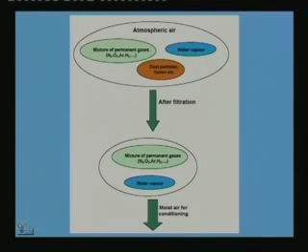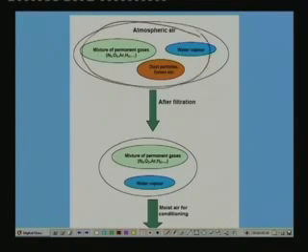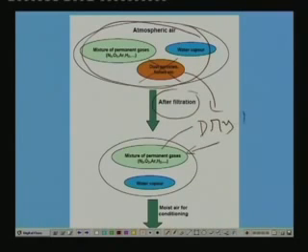So, as I said, this entire thing is your atmospheric air, but in a typical air conditioning plant, what is done is, first of all, we filter this air. When you are filtering this air, you remove the dust particles, fumes, etc. Once you remove them, you are left with a mixture of permanent gases, and you call this portion dry air, plus water vapor. So, this is what is actually processed or conditioned in an air conditioning plant. This mixture of dry air plus water vapor is sent to an air conditioning plant for conditioning. This mixture is called moist air.